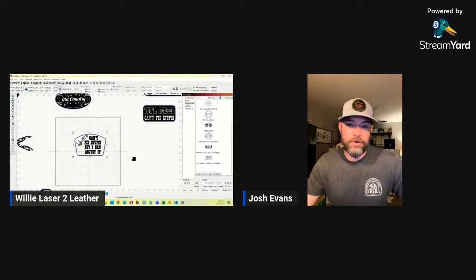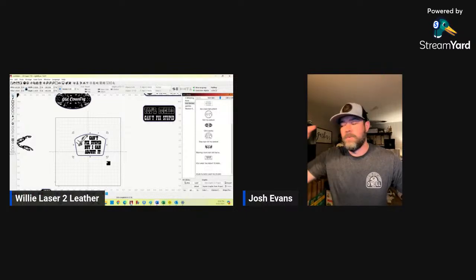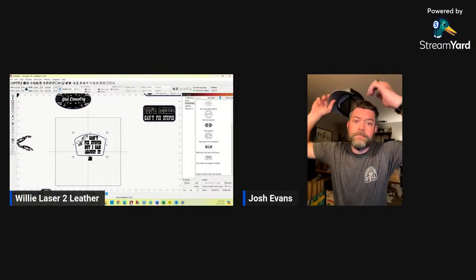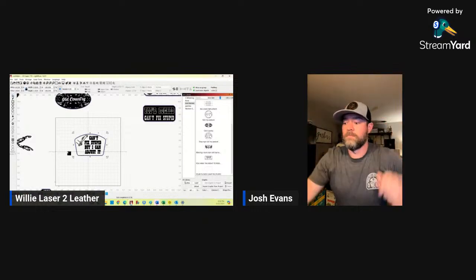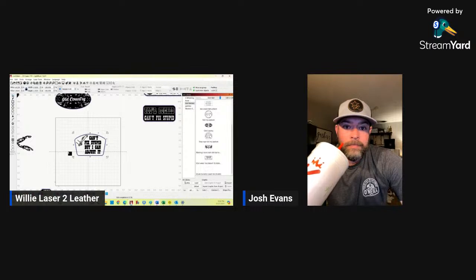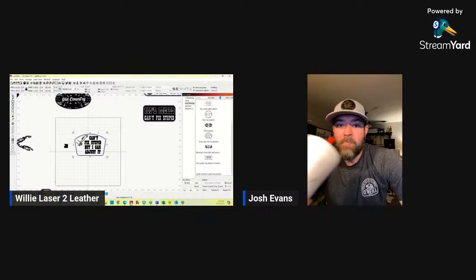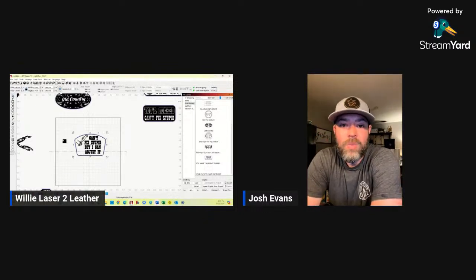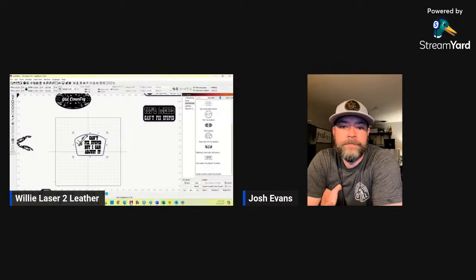Yep, because your 5-watt laser may be somebody's 4.9-watt laser. Or their lenses may not be exactly the same, or they may not be in the exact same focus as mine. The UV laser can be very aggravating because they are very, very sensitive about focus. Even a millimeter out, you can actually see a difference, especially when you're doing glass work.